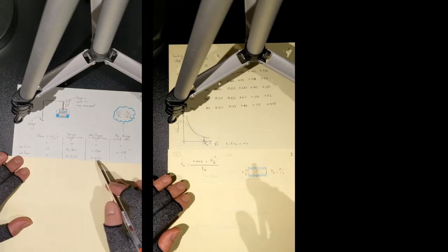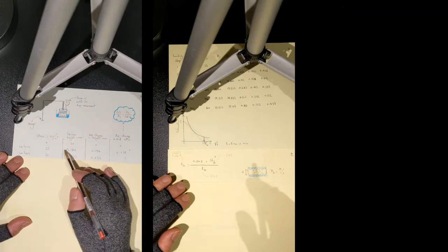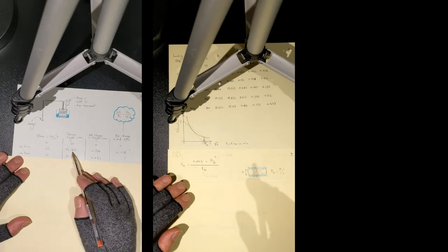In this example, that was 0.073 millimeters, and this will be the change in height of the soil specimen at the end of 24 hours under 50 kPa. And you can determine the delta e again.